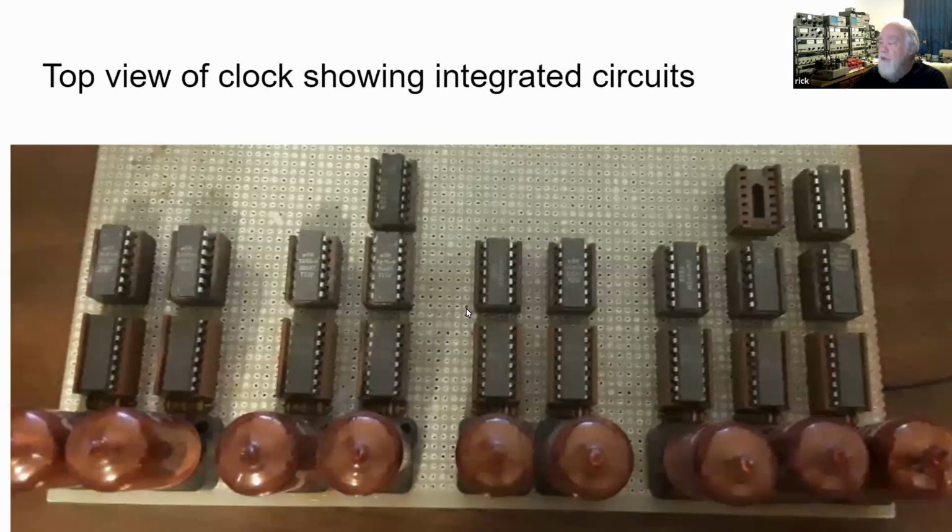If we look at a top view, you can see in this row we have the 4-bit binary counters, consisting of 4-bit flip-flops counting 0 through 9. And then here we have a row of decoders that convert that 4-bit binary number to a decimal 0 through 9 to light up the tubes. In this back row, we have some reset chips because for tenths of seconds and the digits portion of the seconds, we go 0 through 9. But on the tens digit of the seconds, we only go from 0 through 5.